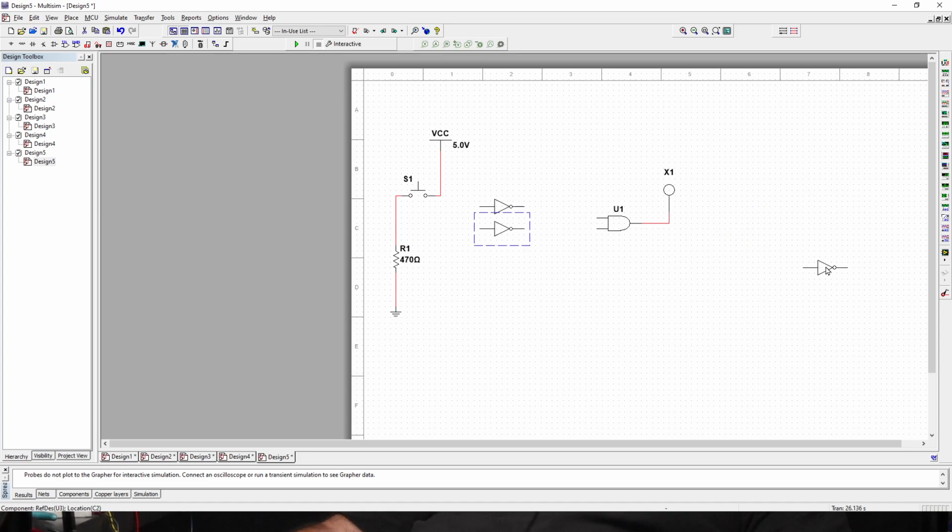Now I'm going to connect those inverters in series. The reason I'm doing this is that there is a tiny bit of propagation delay for the signal to reach from here to there, but it is an extremely short time. By adding those three, I'm adding this delay to that delay to that delay, so I'm tripling the delay of that whole inverter system.